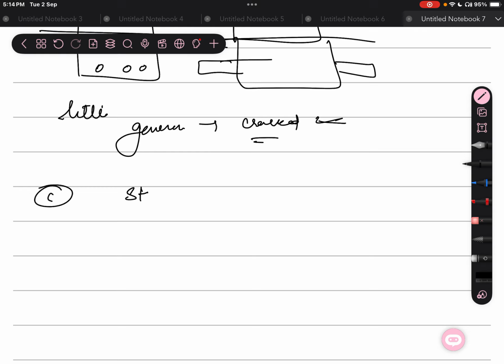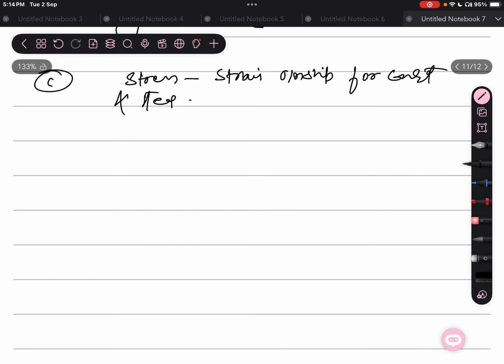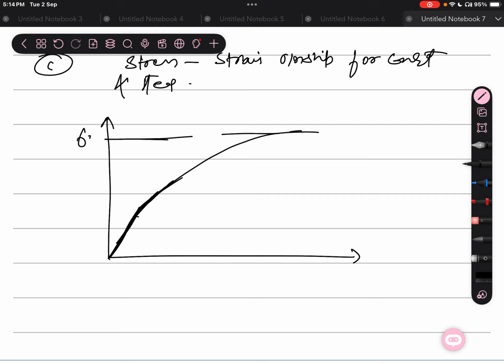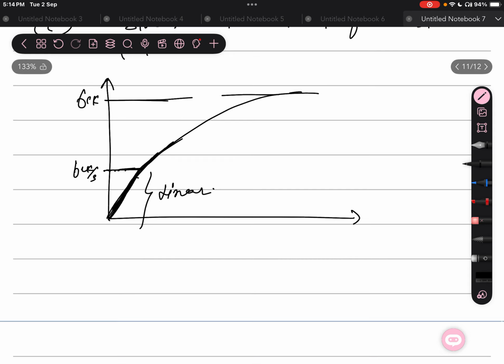Now, if we see the stress-strain relationship of concrete and steel for WSM, in both cases it will take some shape. For concrete, some part will be linear here. This is FCK, and we are limiting our curve to FCK by 3 only. Basically, this is the linear part.